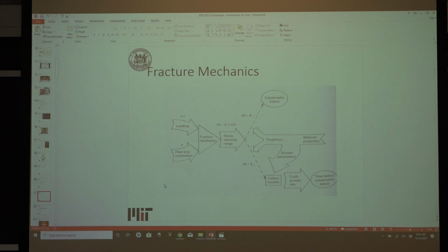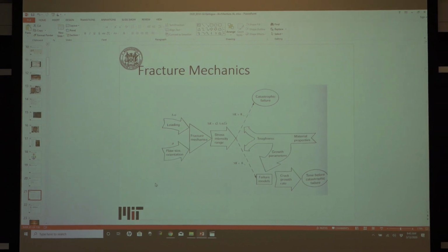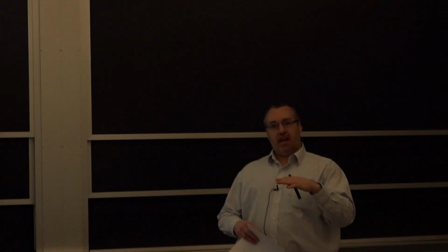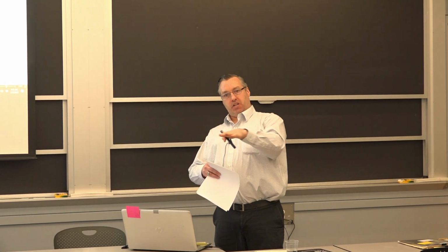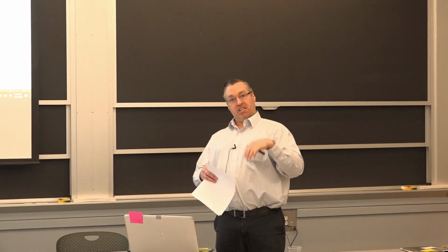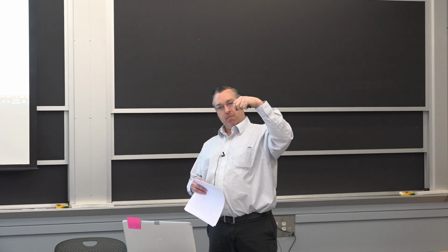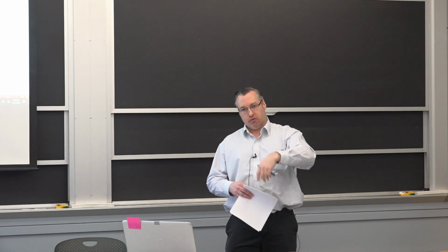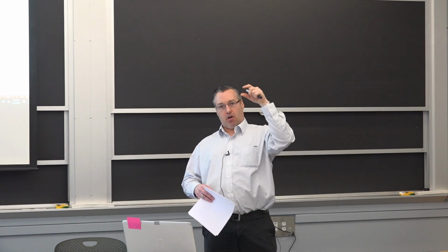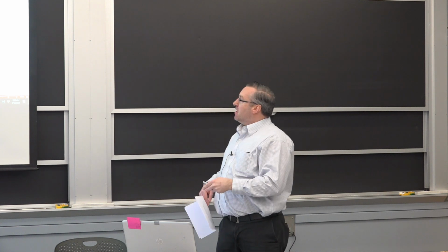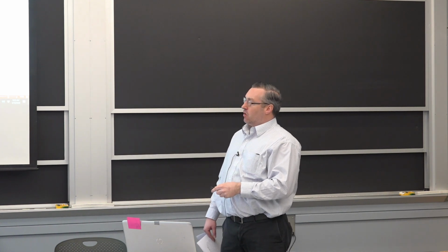So if you have a flaw that's at 90 degrees, that is not a surface cracking flaw but a near surface one, you can use a lot of techniques. And if you're just going perpendicular to that surface, you'll miss it. For an ultrasonic type, if you're thinking of a longitudinal scan, it's just a pulse echo back and forth. You can miss flaws if they're oriented a certain way.